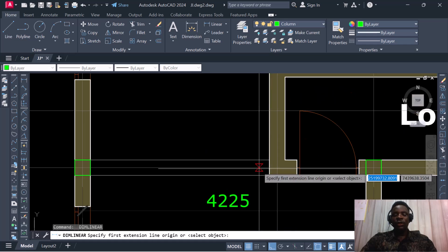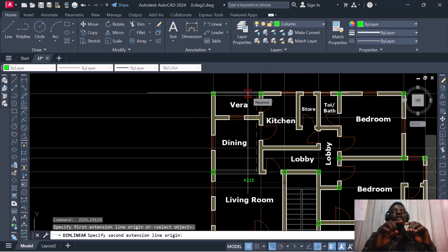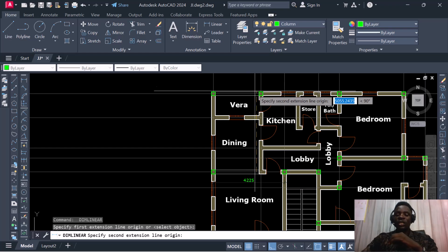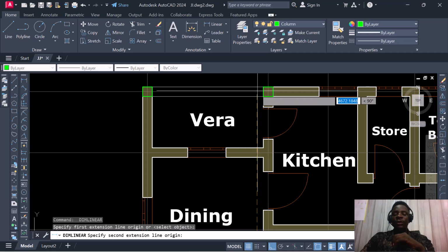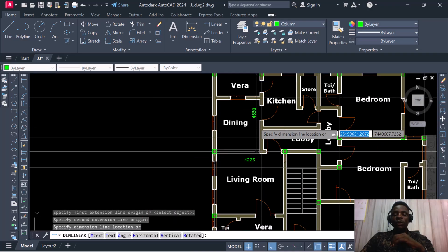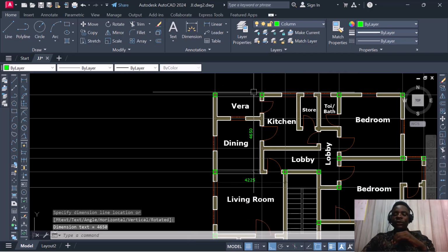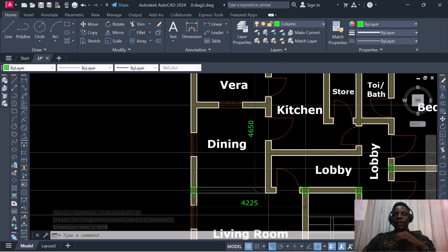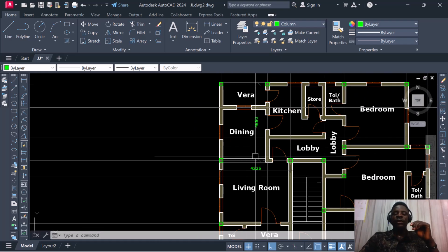Because now when we're supporting our column, we're looking at two things. When you're supporting your beam, we have beam to beam support and we have column to column support, right? So in this situation, we'll be having column to column, and we'll be having this span to be beam to column support and beam to beam support. Okay, so in this situation, you can see here we have 4.6. So we are still within the extent of 5 meter, all right?